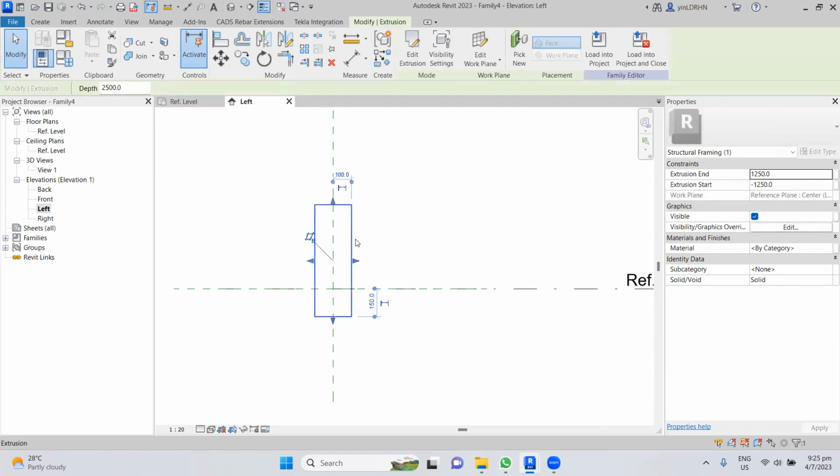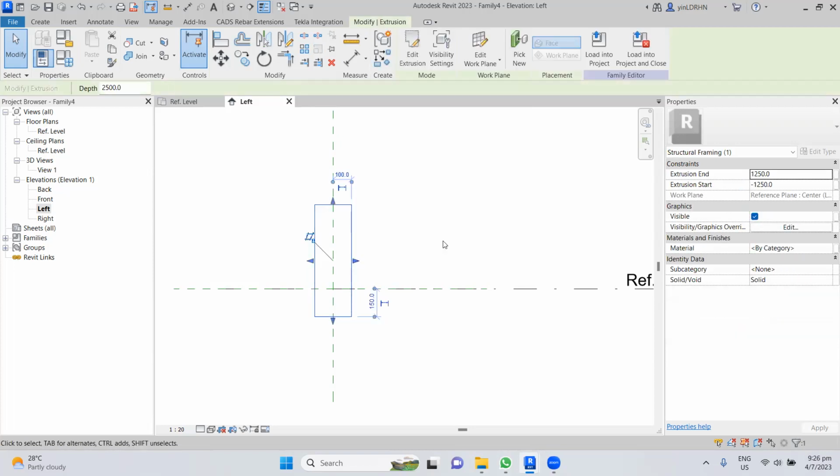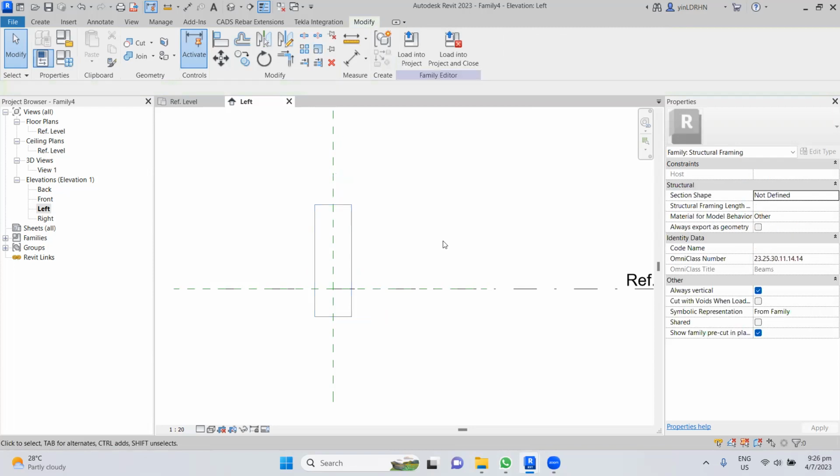Okay. So now my intention is I create a special type of the beam. Okay, rectangular beam simple. We don't need to worry too much on this one, right? So now my intention is to do the T shape or notch beam. Let's say I'm going to do the notch beam, for example. So how I can do, right? So I can create the reference plane here first, right?